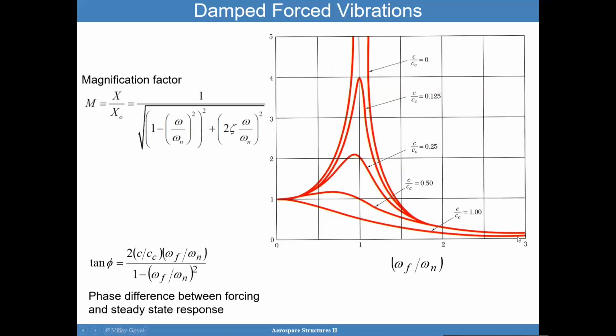So you will see in that situation that it doesn't matter what amplitude I apply, I am not having a lot of success in causing the system to react as much. Because as you can see, x over x naught, where x naught is the static solution and x is the dynamic solution, this ratio is the magnification factor. You can see here there's a very small value, which means that nothing much is going on.